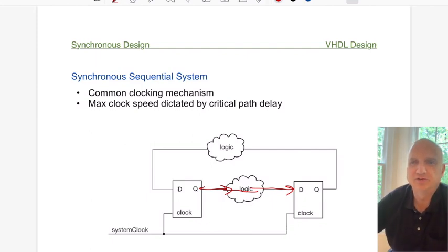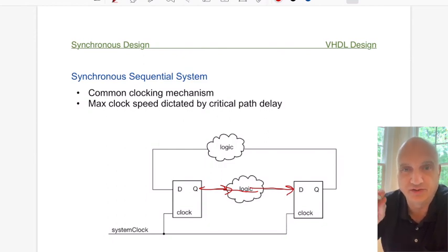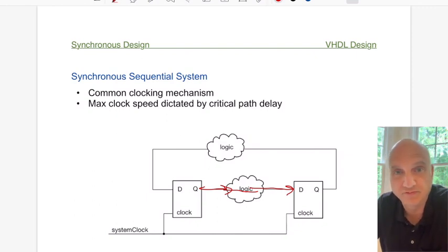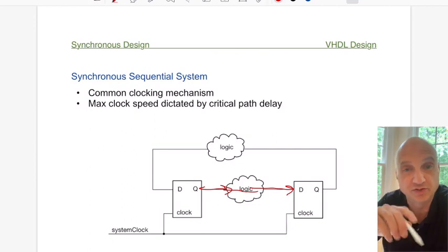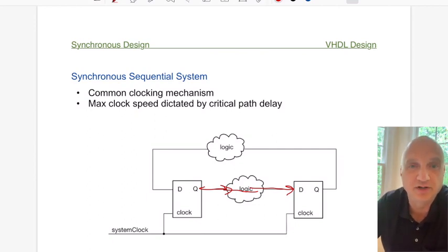There are no typical delays because it really does depend on the device, but you'll see sometimes 7-8 nanosecond delays for logic, and it depends not only on the delay through the logic elements, it also depends on the path delays when they're being transferred from one part of the silicon to the other part. So all of these play a part in driving the delays that you're seeing in your FPGA.